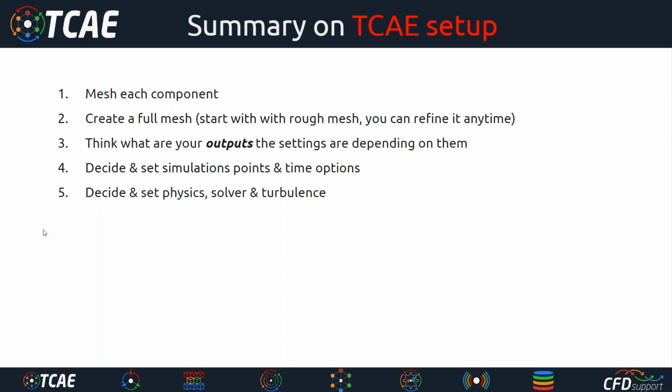Then you definitely need to decide the physics and set the physics, the fluid properties. You need to decide the solver, typically compressible or incompressible. You need to resolve the turbulence properly. Then you definitely need to decide and set the boundary conditions. Boundary conditions are extremely important.